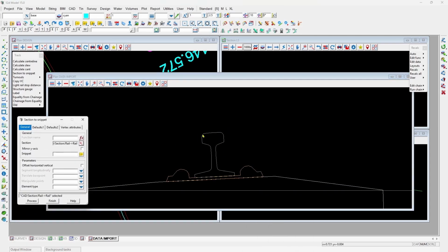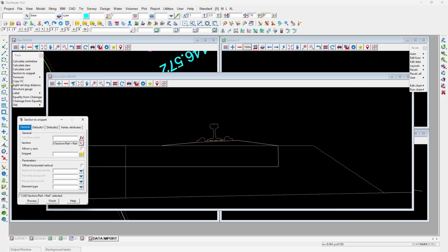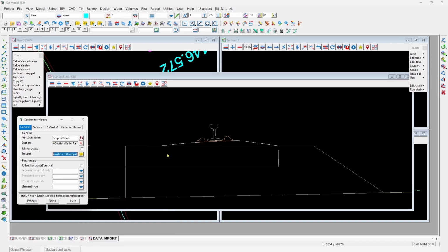These polygons are just drawn as straight lines, and they're just a closed polygon. We can give this a name. We could save these into the user lib so that they're available to other projects. And then for this one, I'll be using on grade, all points on grade, and trimesh element.